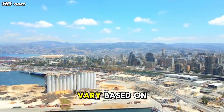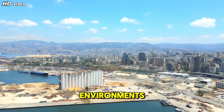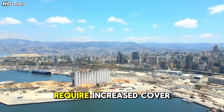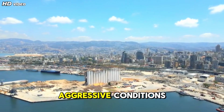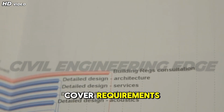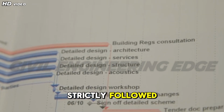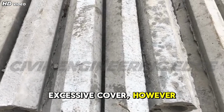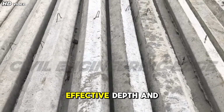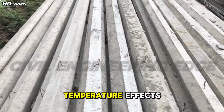Durability requirements vary based on exposure conditions. Columns in marine environments, industrial areas, or areas with high humidity require increased cover to withstand aggressive conditions. Design codes specify minimum cover requirements based on exposure classification, which must be strictly followed. Excessive cover, however, is also undesirable. Too much cover can reduce effective depth and increase cracking due to shrinkage and temperature effects.